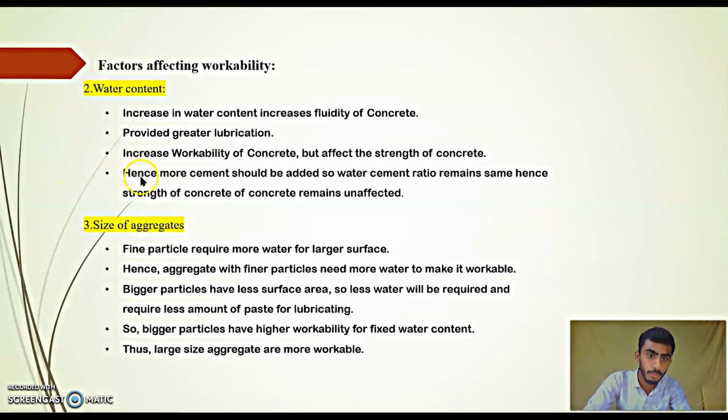Here is the most important point. More cement should be added so the water cement ratio remains the same. To keep it constant, the water cement ratio should be proper. Increasing only the water content is not the proper way to increase the workability. That much amount of cement should also be put in the concrete. Hence the strength of the concrete remains unaffected.